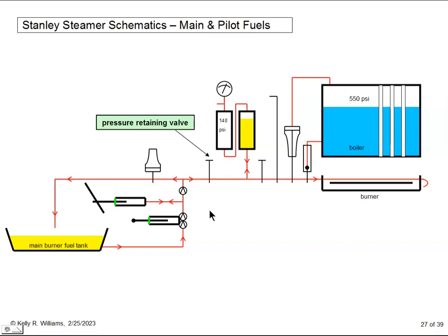And here we should look at what will happen if you forget to open the pressure retaining valve before driving away. The pump will start when the car is moving, but the fuel movement is blocked here by this valve, so the fluid pressure here quickly overcomes the fuel automatic setting, and all the fuel circulates back to the tank. The fuel in the pressure tank is slowly drained into the burner, fuel pressure drops, and steam pressure drops, and then suddenly you remember. And there you have it, the entire main fuel system. A little more complicated than water and steam, but easy to comprehend.